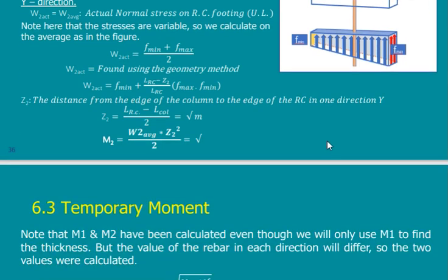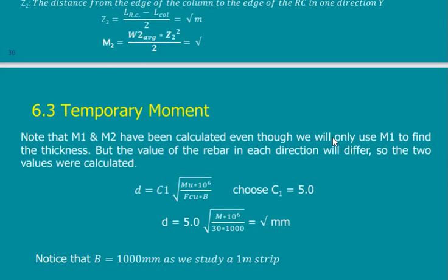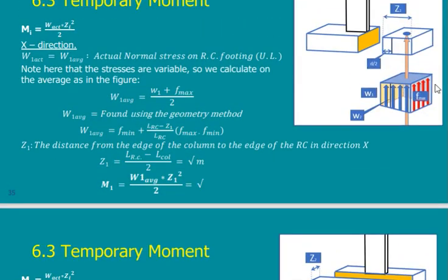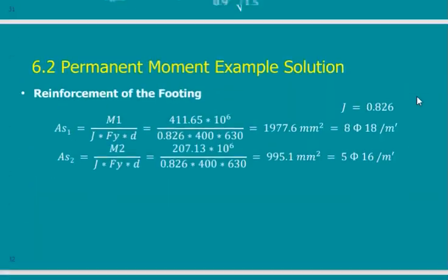So anyway, as a general rule, either you calculate the moment due to the full width of the footing, and in this case, when you get the moment, just divide by the length of the footing to get the amount required per meter. Or if you can use each meter similar to this direction, if you can do it by meter, it's okay, never mind. What is important is what you are going to write on your drawing.